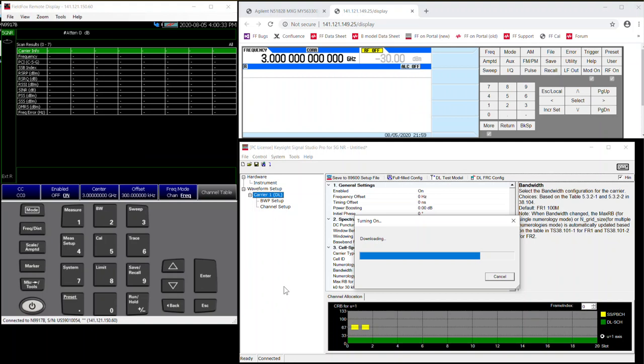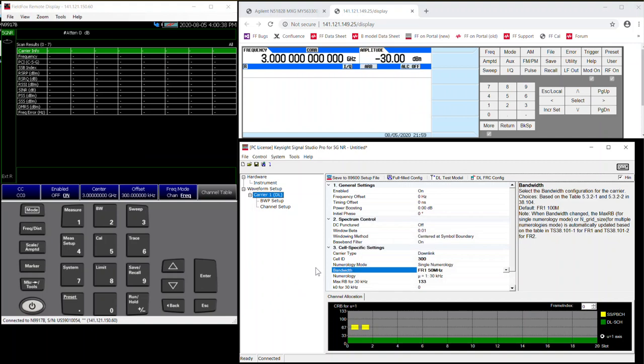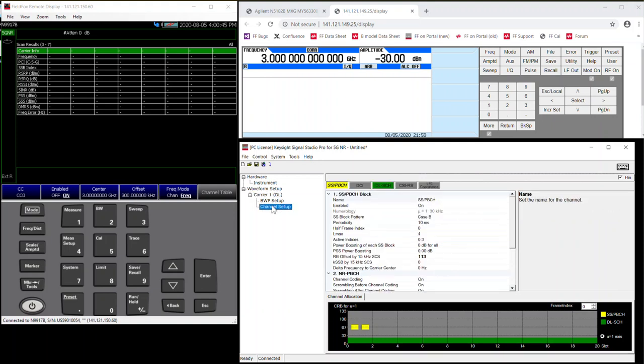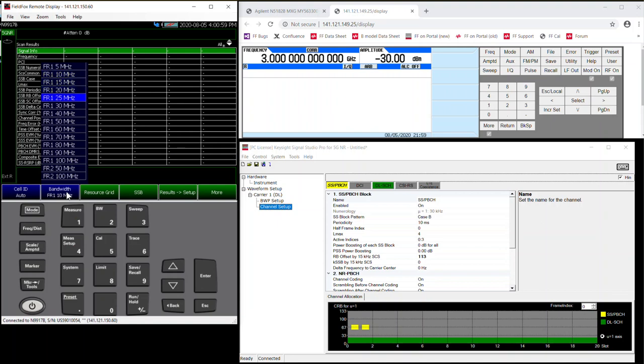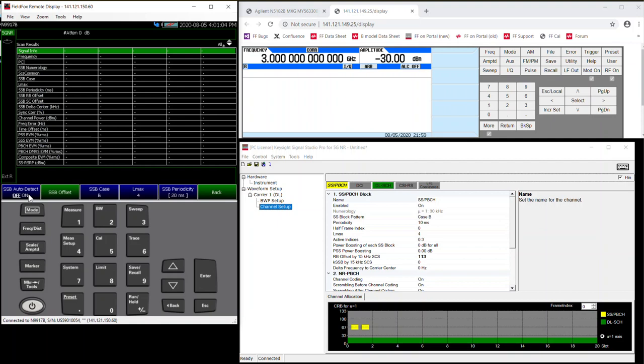But actually, before we go there, I wanted to also show you just quickly that you could use VSA to communicate here. Let me go back, I guess we could let it be at this frequency. This will take a little bit longer. Oh, now we're back to 0, so we have to make this 0 again. There it is. That's my 50 megahertz. But if you want to go into conducted, I think I have to tell it that it's 50 megahertz. And let's turn offset detection off so it's a bit faster. And I think this will bring it up.